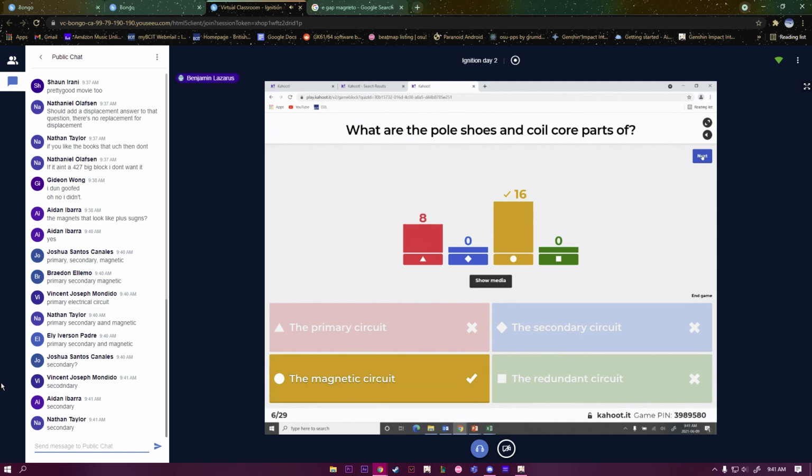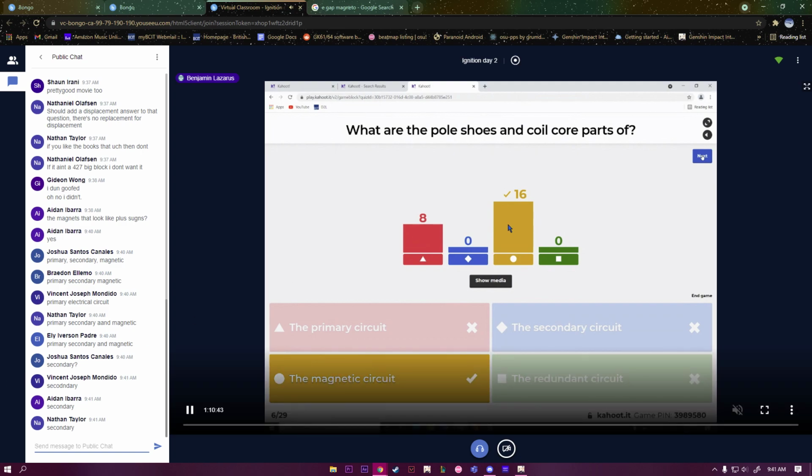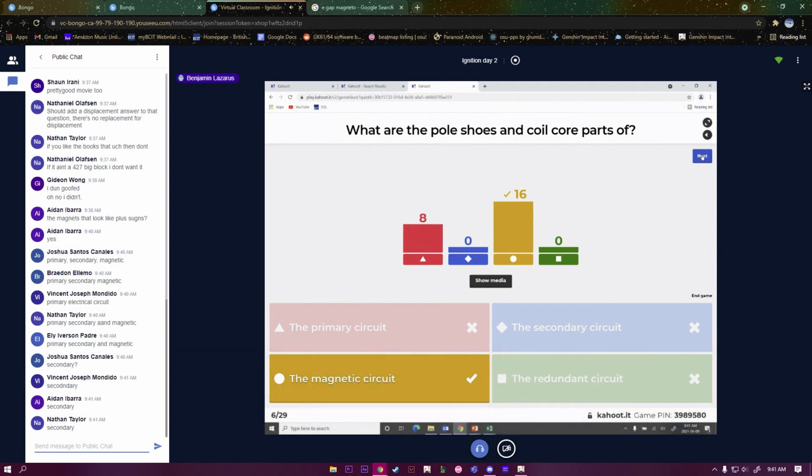So the distributor now, instead of having to control 20,000 volts, only controls 200 volts. And 200 volts is pretty tame stuff. It does what we tell it to do. You can probably stick your fingers in the socket and most of the time survive with 200 volts. Don't try it. This hasn't been recorded. But 200 volts is fairly survivable, and it's pretty tame. It'll go where you tell it. 20,000 volts, that's a different animal. It does what it wants.